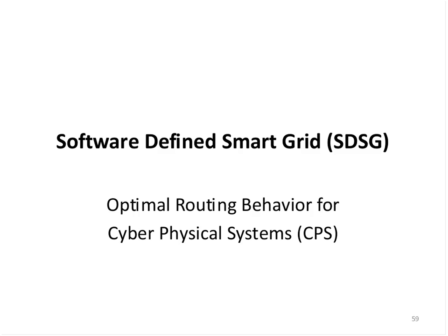I guess I'm going to answer it this way, because there are some needs to have new spectrums when you think of wireless. In fact, I didn't put it in this presentation, but we are doing some work now to use VHF, very high frequency, which only has a bandwidth of 10 kilohertz to 20 kilohertz, versus we talk megahertz of bandwidth required in the gigahertz spectrums. We also have a huge amount of bandwidth that's been released from the television systems that were shut down some years ago. Those original bandwidths were 6 megahertz.